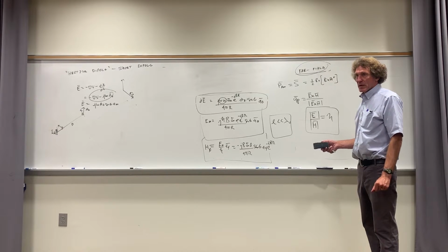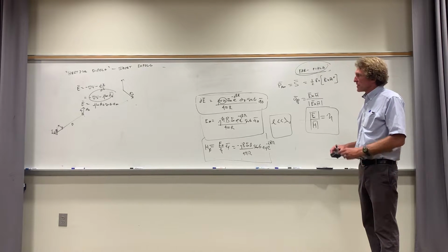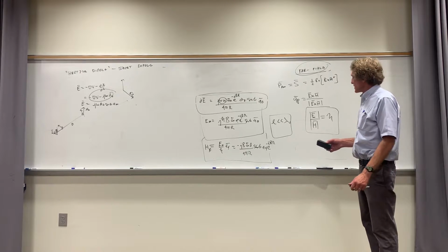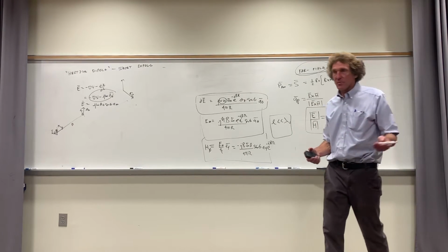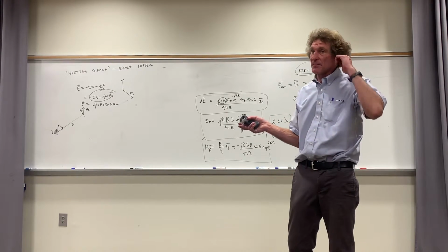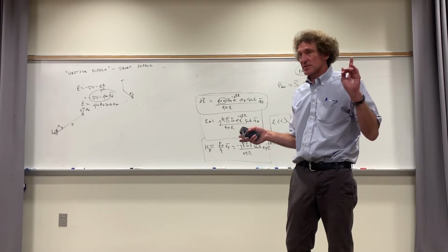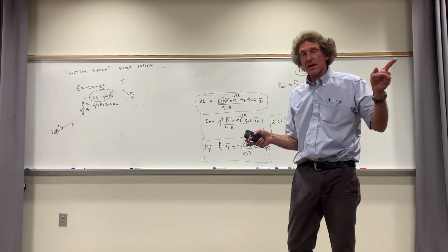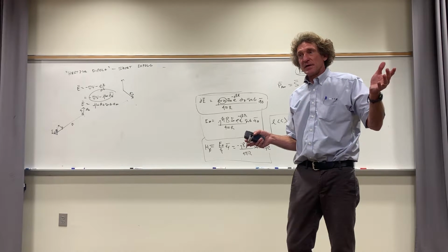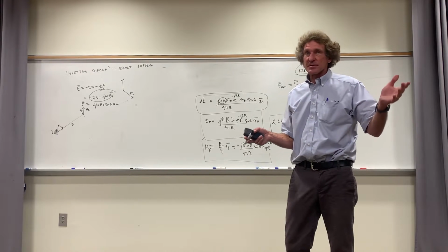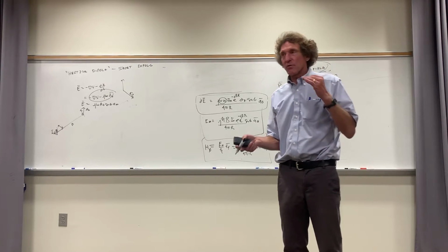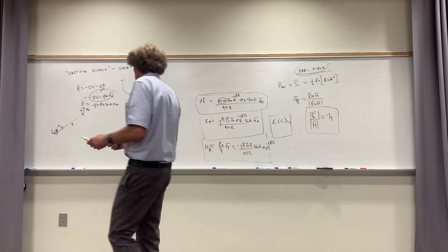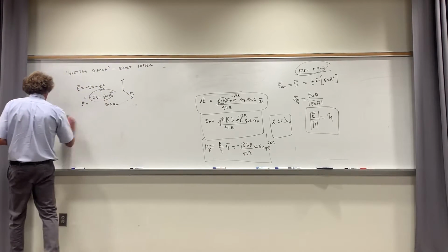All right. Now, he has this in his book. This is in the far field. Let me show you a few things now that are important. First, the relationship. If you have the E field in the far field and you want the H field, you just divide by eta and find the direction. E cross H is in the direction of power propagation. The next thing we have to do, and these are fairly important, is find the power density and then the total power radiated.